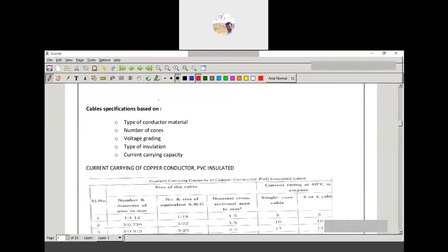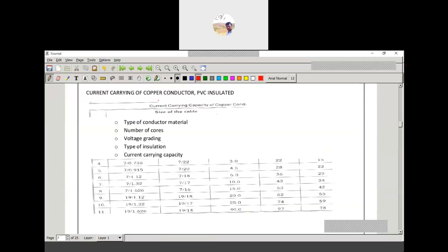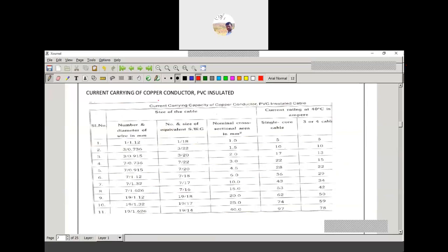According to the type of wire used, here is the winding: winding combination, single cotton covered, double cotton covered, and enamel coated. In the machines we have windings, the armature winding and field windings. For that purpose we are using single cotton covered and double cotton covered. Each winding having the wire will have insulation around it, which is single cotton covered, double cotton covered, or enamel coated wires.